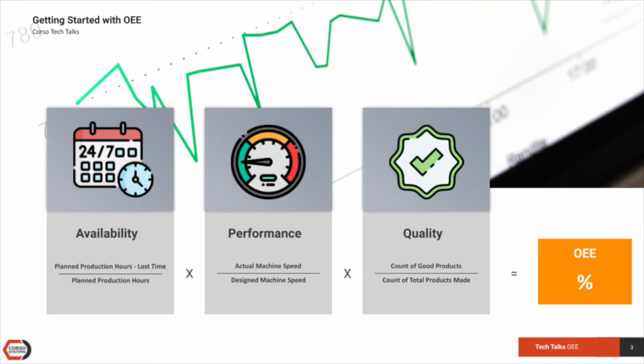So there are three different ways that we can break down that OEE number and give us some more granularity on what was actually causing the problem. And that's ultimately how these three numbers are interrelated. To get that OEE number, that single number, we simply multiply the availability times the performance times the quality, and that aggregates them all up into a single number.